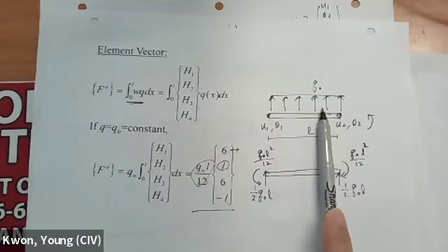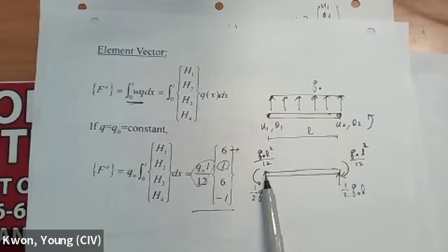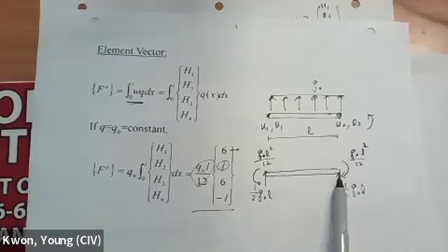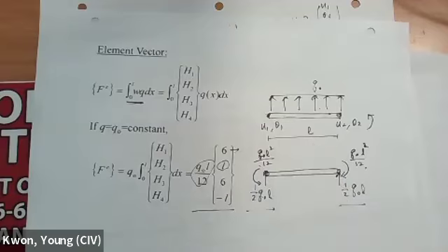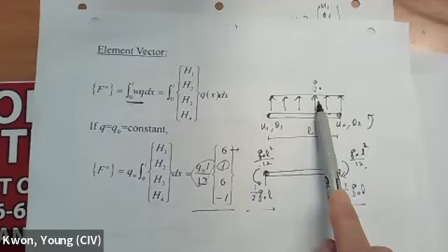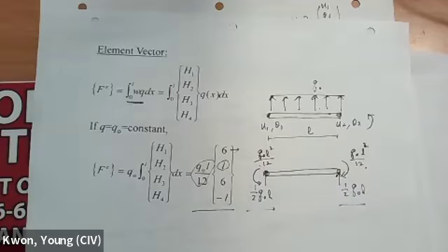So we have to find an equivalent flux or equivalent load at the nodal point. That means here, this force and this moment at the nodal point are going to represent this. Right? So this is the actual problem, and that is the finite element representation of this node in the formulation.